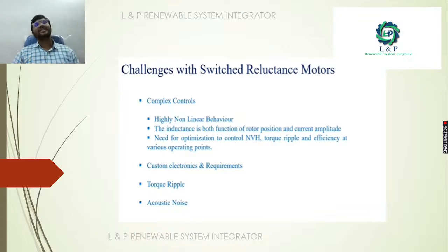And what are the challenges in the switched reluctance motor? So control is a little complex. We have torque ripple formation, and there is a possibility for acoustic noise to be created. And we need to have better optimization for NVH.